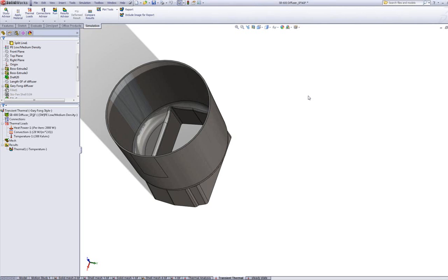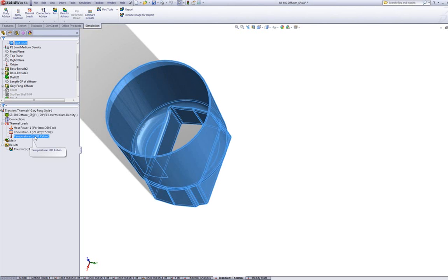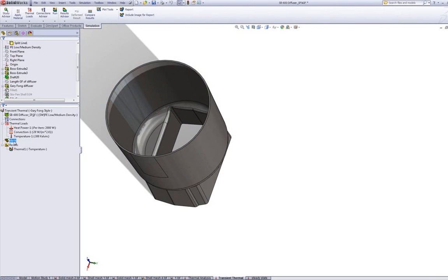All right. So again, we've done a transient analysis. We've designated the time domain and the time step. We gave it its initial condition of room temperature for the whole volume. Now we can go in and run the study again. Now I ran the study. As far as our mesh, I chose the regular mesh. Let me show you what that mesh looks like.